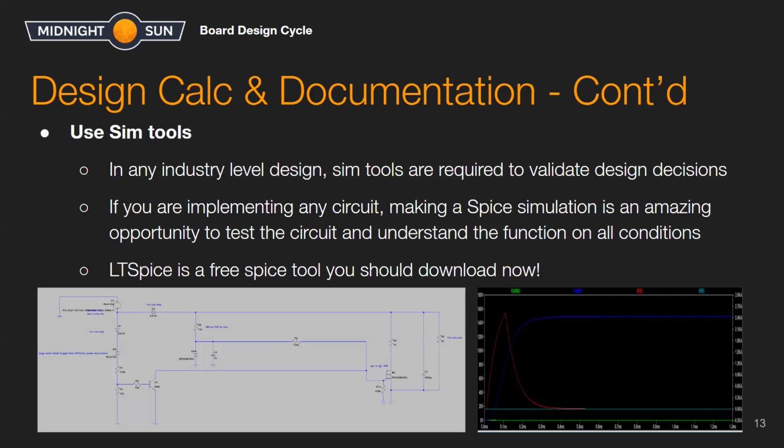Yeah, and for some of them that include ICs, it's a little trickier to do. Sometimes you can find SPICE models for them, but typically it can be simplified. Say a load switch can be simplified into just a straight MOSFET. Yeah, for sure. Also, LTspice is made by Analog Devices, so all their ICs will be found on there. In most cases, you can find your components on DigiKey and they have SPICE simulations with them if they're well-used ICs. But if they're not, you can hopefully find an equivalent on LTspice in the Analog Devices supplier. So yeah, it's still possible.